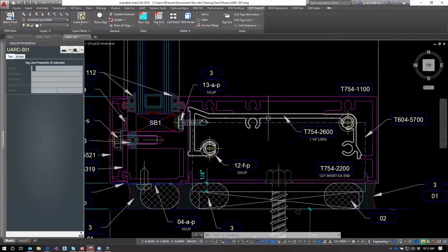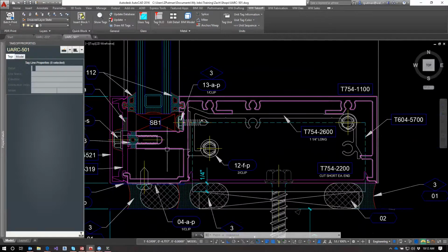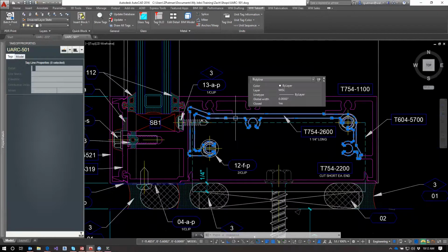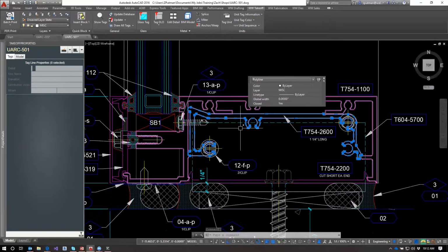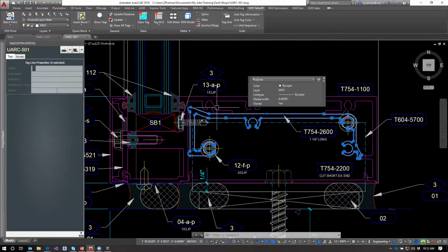In addition to those 4 parts, we have this part here, which is a shear block clip. This attaches to the vertical so the horizontals can sit on it and be attached to the whole wall. We're going to need 1 on each side. I don't think it actually says here, but yes, the shear block clip goes on each side of the horizontal.